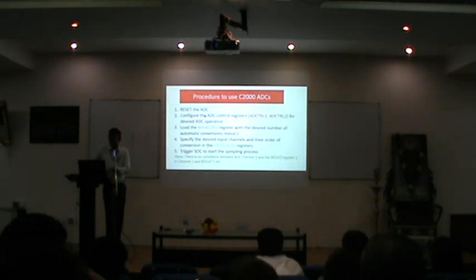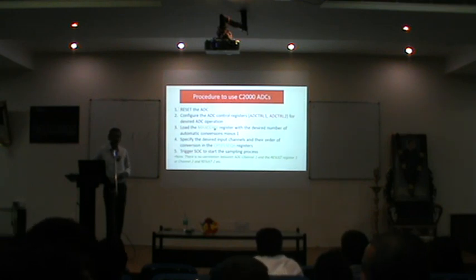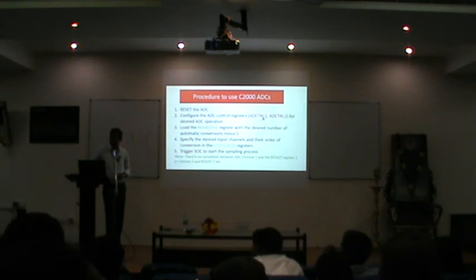Just a small thing. Just like your PWM module, here also you have setup procedures to be followed, starting from resetting the ADC all the way to triggering the SOC signal in order to start the conversion process. Once again, all of these things can be done only after configuring these peripherals properly. So you have something called the control register, the maximum conversion register, channel select registers, all of these things should be configured.